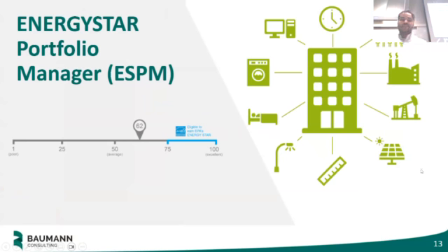But again, where we stopped was Energy Star Portfolio Manager. Before we start working on any energy efficiency project, we need to first understand how a building is currently performing. That is known as benchmarking, where you verify the performance of your building against others in the same climate zone and the same building type. Energy Star developed their own tool, Energy Star Portfolio Manager, that gathers all the utility information about a particular building, then does a normalized weatherization and accordingly determines the performance of your building against the others.